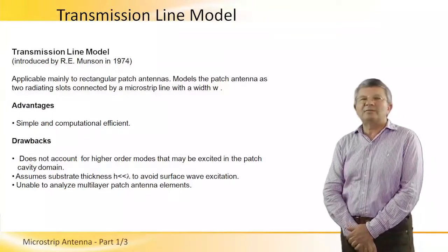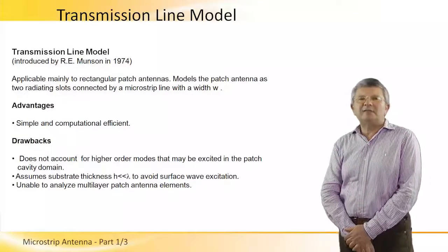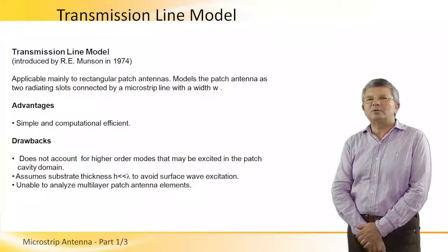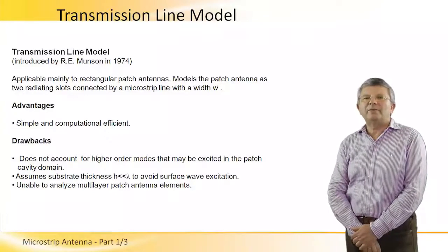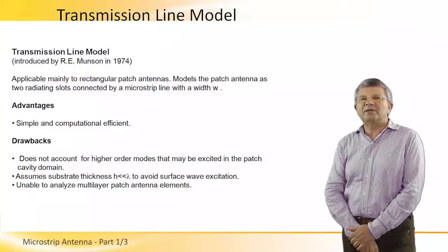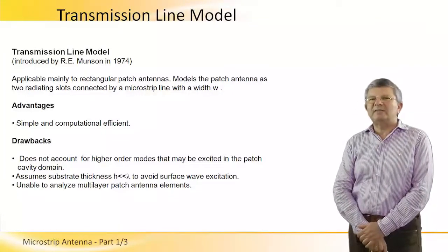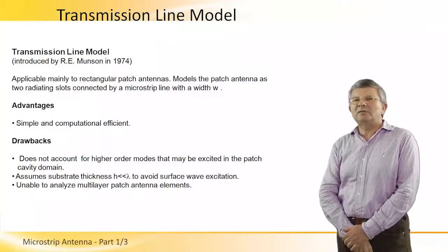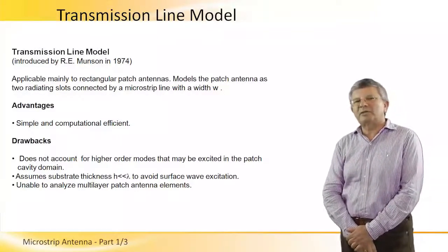However, it does have some drawbacks. The first one is that it does not account for higher order modes that may be excited in the patch cavity domain, as we will see later. It assumes a substrate thickness H which is much, much less than the wavelength, in order to avoid surface wave excitation in the substrate that supports the patch antenna.